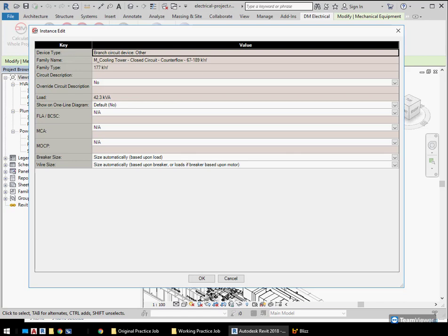So Revit can, I think, do the motor calculations at the feeder and service level, giving you 125% of the largest if it knows that something is a motor. But otherwise, it doesn't do anything with the fact that you've got motors in a project and they need to be handled a little differently.